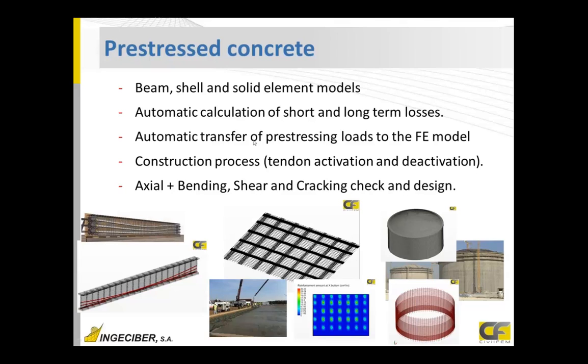These are loads that can be combined with the construction process or any other type of loads, and after that you can check for axial plus bending, shear, and cracking checking. So here you have a model that is a foundation slab with pre-stress, and here you can see results as they apply this pre-stress and the different loads.